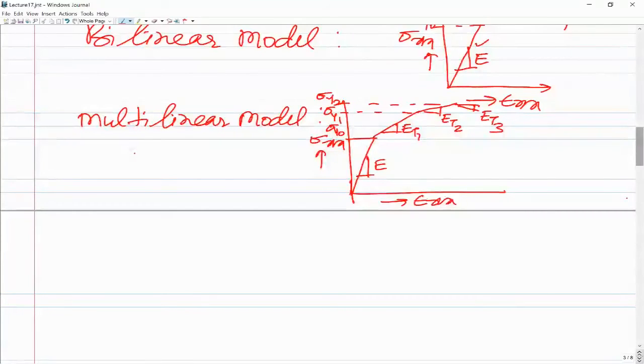Okay, sir. So all this derivation which we have done is for isotropic, right? Yeah. So far whatever we have done is isotropic, but if you use the appropriate yield function and the constitutive matrix C, the expression for CT will be the same. The tangent constitutive matrix expression is going to be the same. Your F yield function would be different. The C matrix would be different.